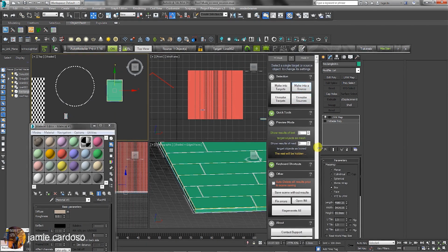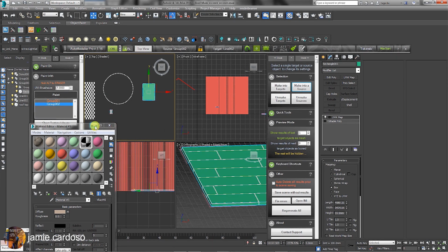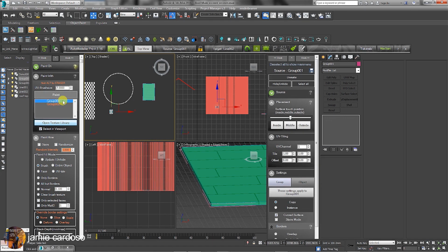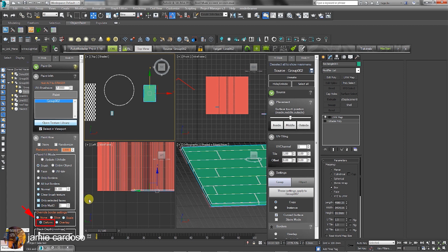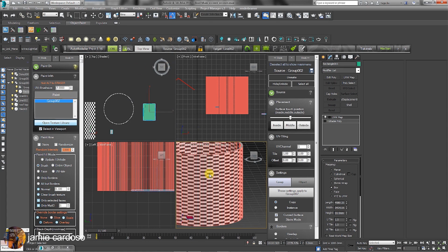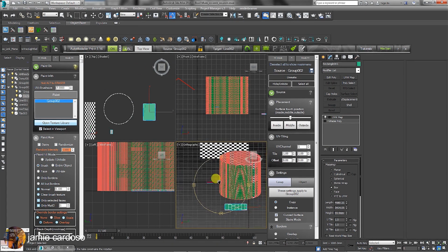Open the Properties dialog and make the new tile into a source as previously done. Open the Paintbrush dialog. This was the previous mesh source. Let's delete it by simply selecting it and pressing delete on your keyboard. Because you'll be painting on a cylindrical surface, let's change the override border settings to deform. Enable the paint button and begin painting tiles onto the cylinder.